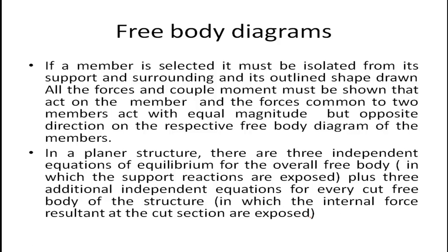Now, before moving further, you should know what a free body diagram is. If a member is selected, it must be isolated from its supports and surroundings, and its outline shape drawn. All the forces and couple moments that act on the member should be shown, and the forces common to two members act with equal magnitude but opposite direction on the respective free body diagram of the member.